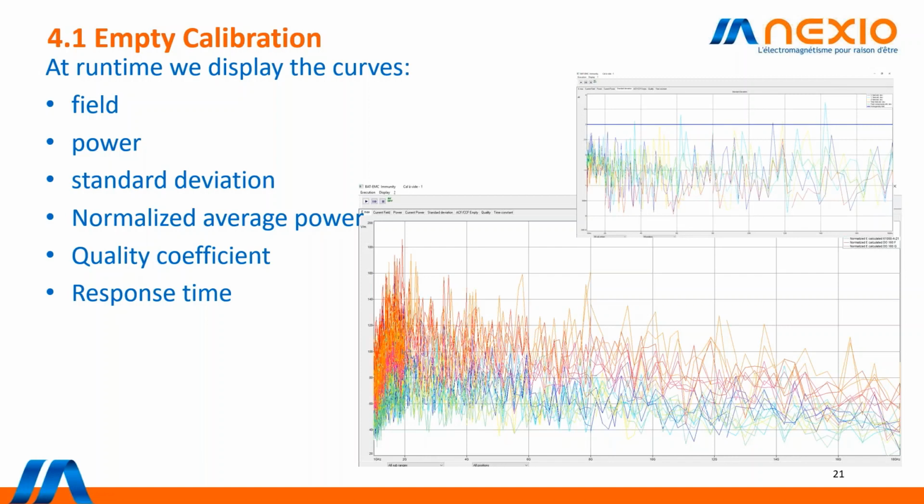So you mean to say at each frequency you make a field leveling, then you rotate the stirrer one complete rotation, correct? So the stirrer is rotating continuously, so it's always moving, and we do leveling, as you mentioned. When we reach the target, we wait one complete rotation to be sure that the equipment received all the different possible fields from the different positions.